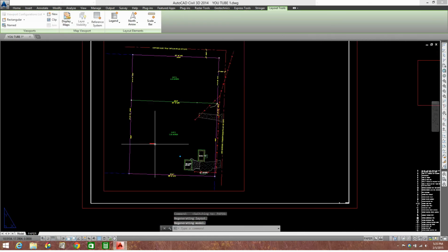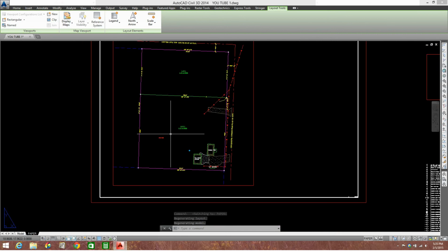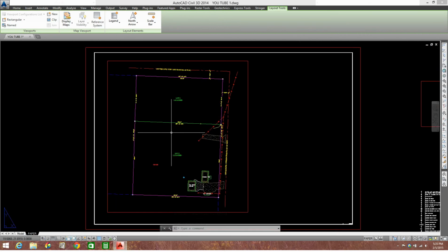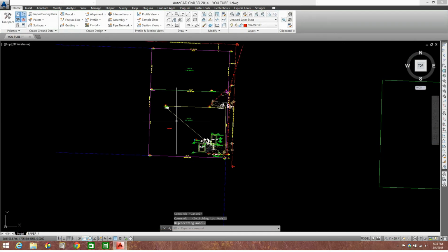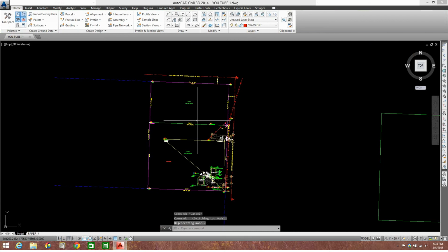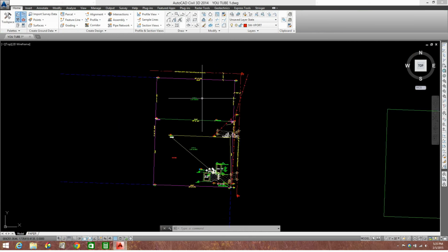Now that shows up. This is also handy when you have, say, a plan set or whatever. You've got multiple viewports, different scales. You can have all those sorts of things but only have one model space. There's no reason to have multiple drawings when you're all working off the same thing. You just modify your paper space.